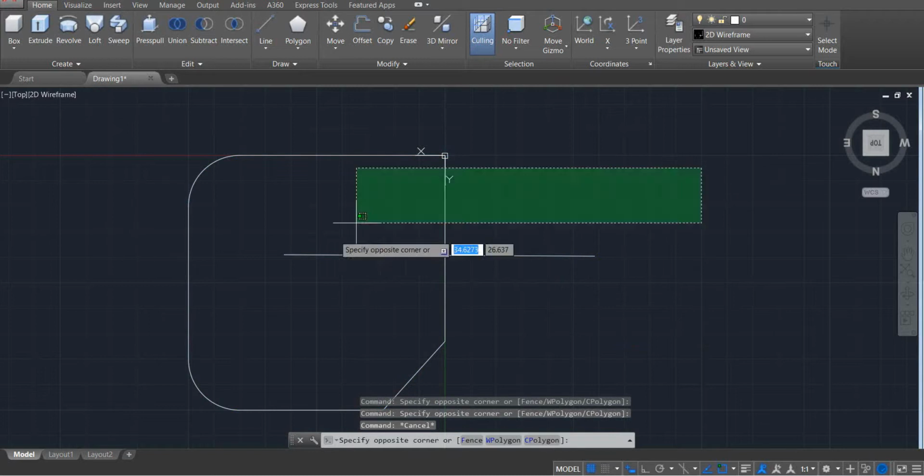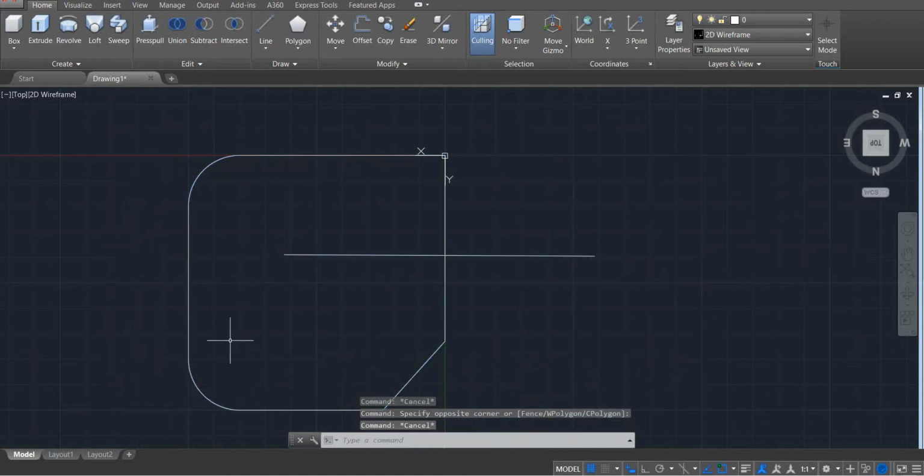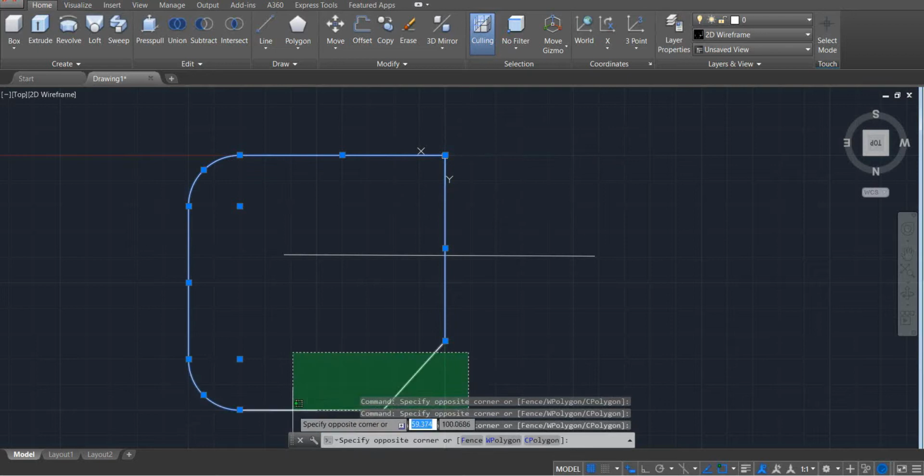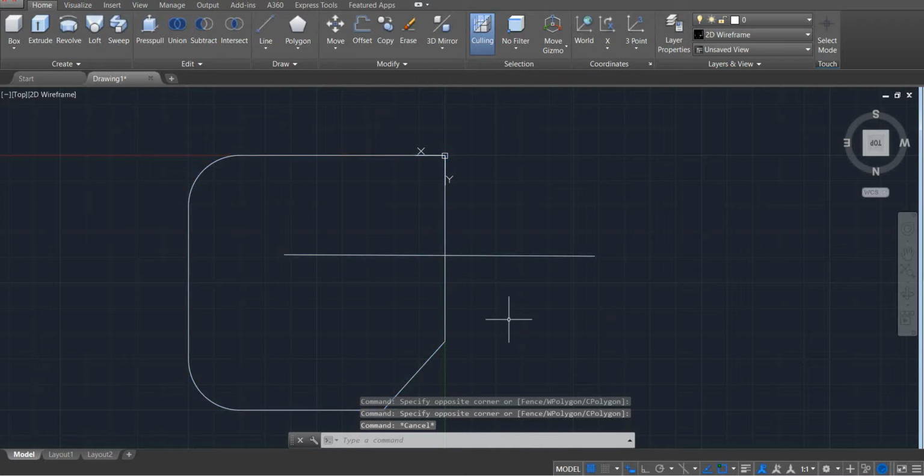If we decided to do extrusion to all of this two-dimensional sketch, it won't be extruded. There is no extrusion in this case. Why? Because we do have two loops. All of these lines are forming one loop, but this loop is closed, so that is fine, it will be extruded. But this one won't be extruded. Why? It is an open loop.